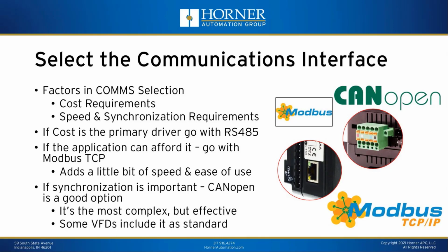But again, if the application can afford it, certainly I would recommend going with a Modbus TCP type approach. Now, another factor could be synchronization. You might have multiple motors that need some level of synchronization. If that's the scenario, then CANopen is a good choice. I know a lot of people don't think of CANopen communications when they think about variable frequency drives. CANopen is a very popular field bus network that is extremely popular in Europe. A lot of drive manufacturers support CANopen, some of them even natively as built in, even without extra cost. I know that Lenze offers that as a standard option on many of their drives in addition to Modbus. So CANopen is an option you should not forget about.